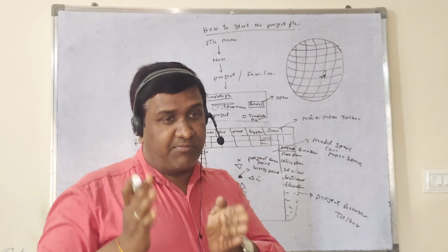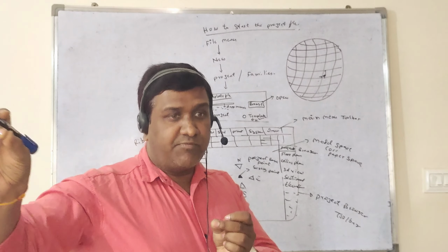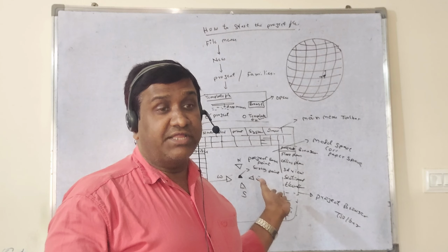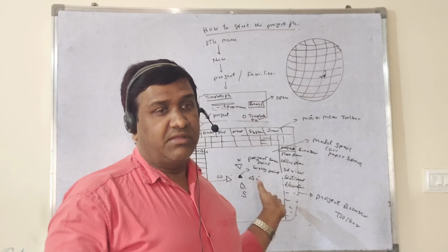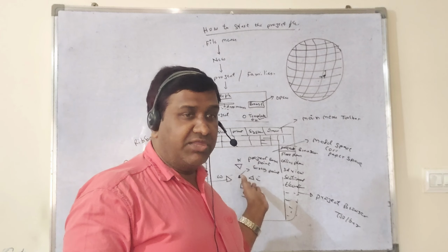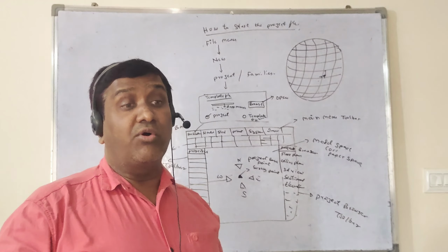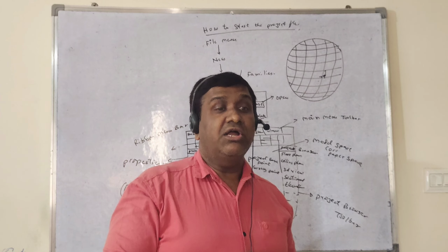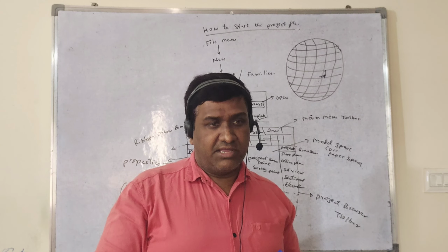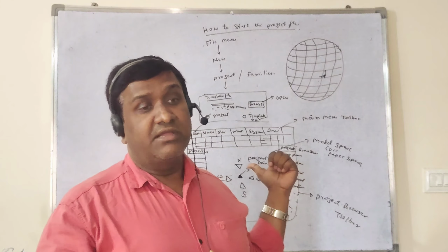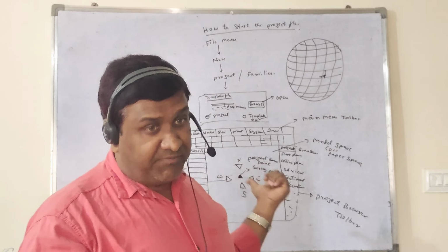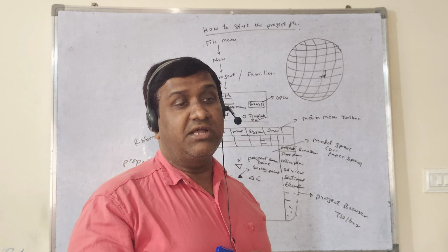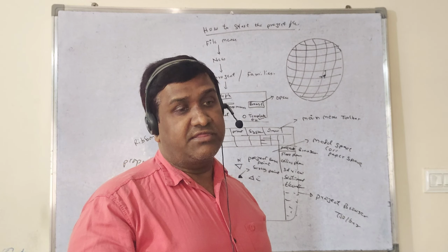So exactly when you give the coordinate points, they are automatically taken through the internet, because your system has to be connected to the net. In the options there is one menu, Manage. In that Manage menu there is a Location menu. With the help of that Location, we have to update the coordinate values, because you don't know the coordinates. But here, with the help of the internet, GPS tracking, and Google Maps, we can take the location point of the coordinate values, XYZ.